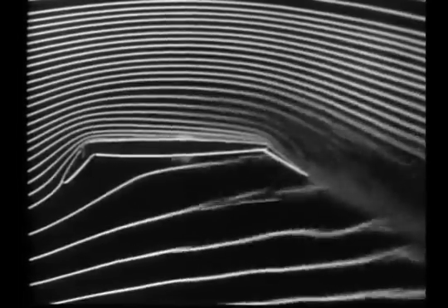Although this film has been concerned only with aeronautical applications, similar techniques can be readily applied to diffusers, bodies of revolution, or fluid machinery. Boundary layer control may, in fact, be applied wherever the transition or separation of the boundary layer affects performance.